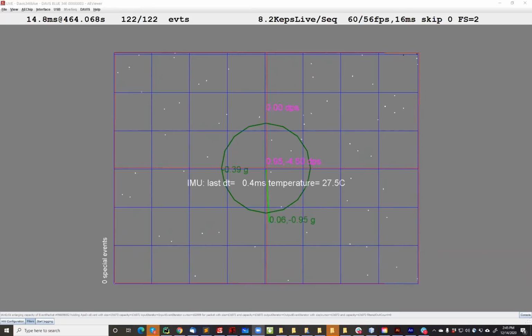Okay, so any other question? Yes, I have another question. So did you just set what's the stabilized position at the beginning, or do you have to reset it every time? It's high pass filtered right now. At the moment, it's just high pass filtered. So it only takes the high speed motions. You see when I moved it and then it kind of drifted back. Yeah, it just kind of removes the DC component of the rotation. So it's designed to keep high speed motion stable.